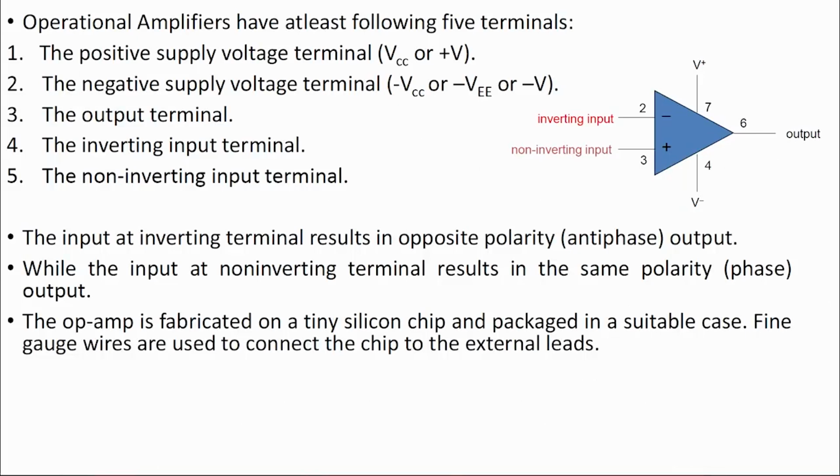When we talk about op amp, generally we will see 5 terminals. Actually this op amp is an 8 terminal device, but most of the time we talk about 5 main terminals: positive and negative supply voltage, output terminal, and inverting and non-inverting terminals. Pins 1 and 5, which you cannot see here, are used for offset, while pin 8 is not connected.